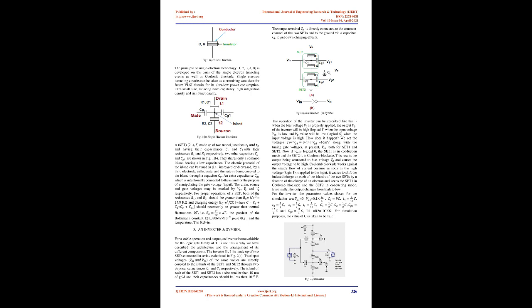2. Tunnel junction and single electron transistor. A tunnel junction is made up of two conducting materials and a thin insulating barrier between them. The tunnel junction must have a capacitance C and a resistance. The conducting electrodes of the tunnel junction will be a superconducting or semiconducting material. When we are considering them as superconducting, electrons, having one elementary charge, 1.60217662 times 10 to the power minus 19 coulombs, carry the current through the junction.